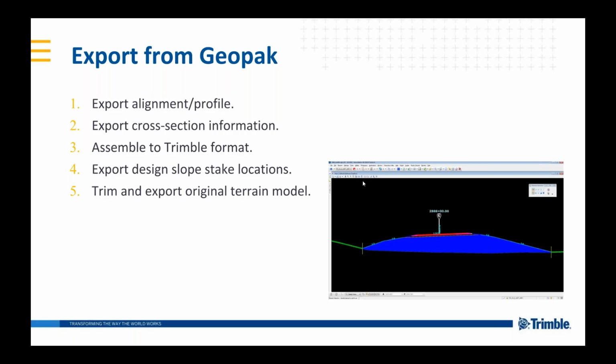And as well, we will export out the original terrain model, and this is for purposes if we find some things that aren't fitting out in the field. This helps us do some field checks and figure out where our original terrain is, where we might need to do some fixes. We need to do some infills with our field work.